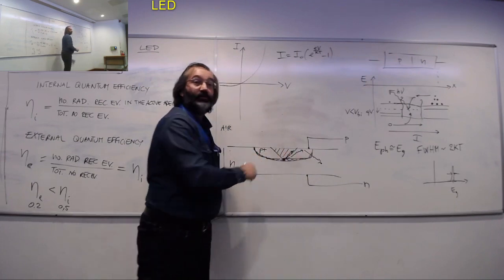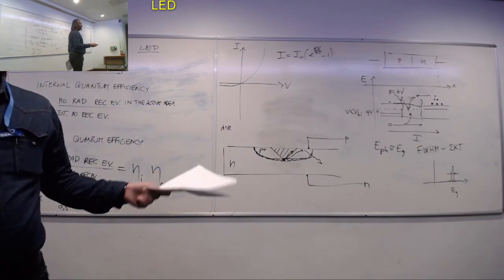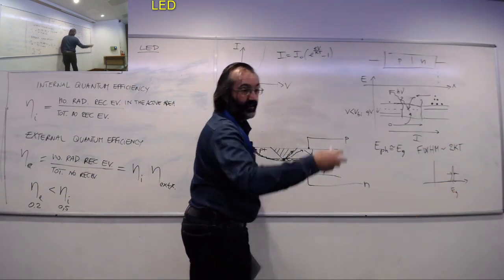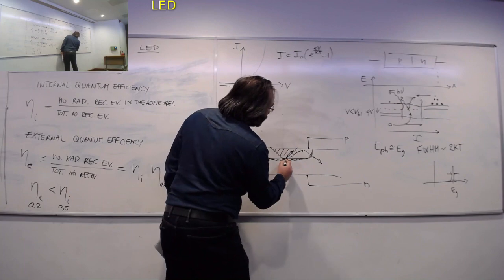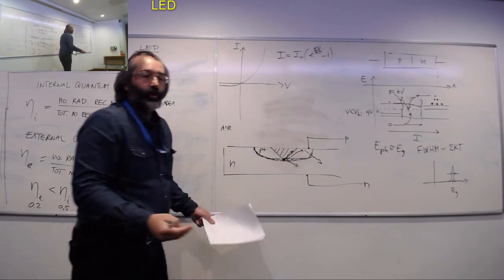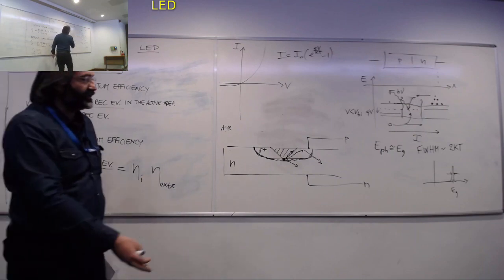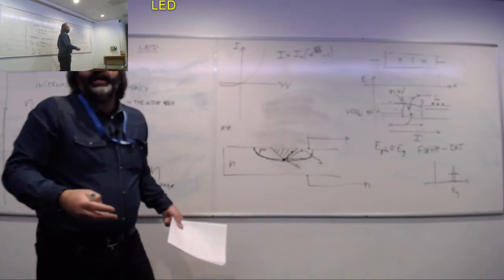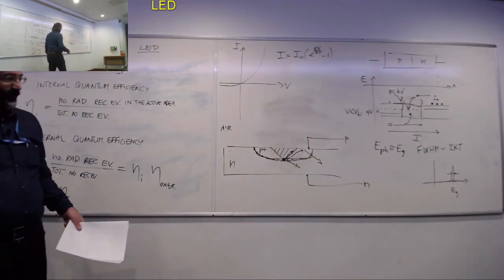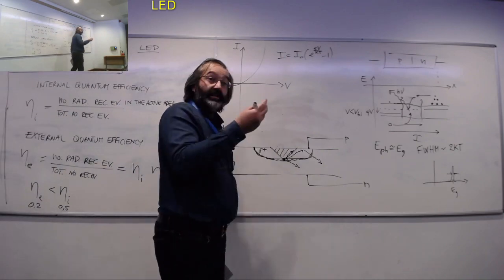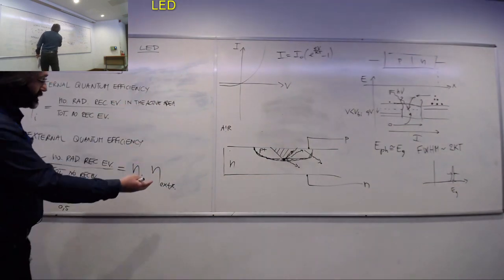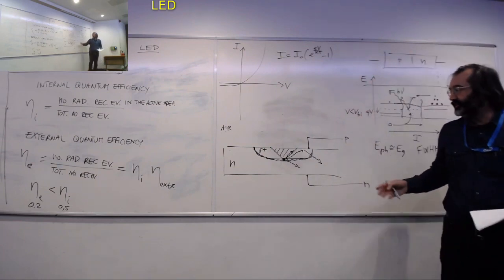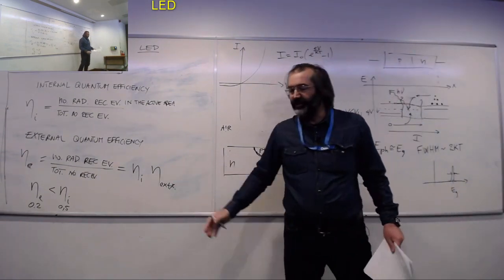Whatever goes out of the cone of light is effectively turned into heat. So total reflection is one process which ends up in the end also in being transformed into heat. Also, remember, Auger absorption is always there, so there is always a chance that a photon emitted in that direction is absorbed by an electron and then turned into heat anyway. So there are all these things to take into account to maximize this. This is one point someone needs to consider to maximize the extraction efficiency.